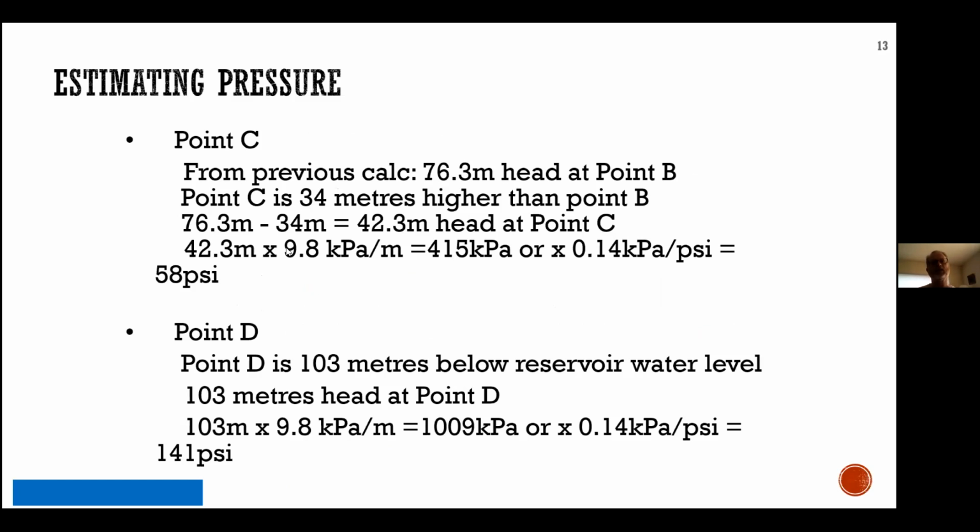But here's the key, 9.8 kPa per meter. So as long as you get the right elevation in meters from the measuring point, whether that's the bottom of the reservoir, the top of the reservoir, they could ask you whatever. They could say the reservoir is half full, but it's 6 meters high. Okay, now you know it's 3 meters. And then you can do your calculations from there. So just work at it sequentially from that point.